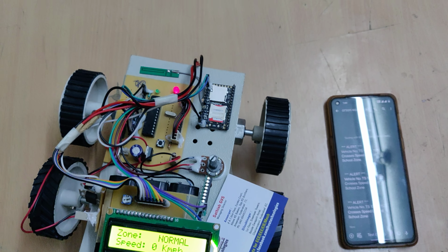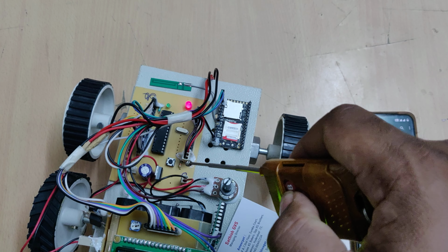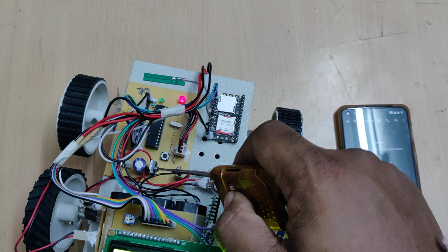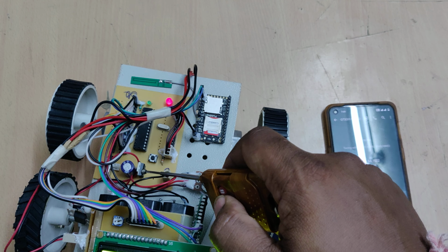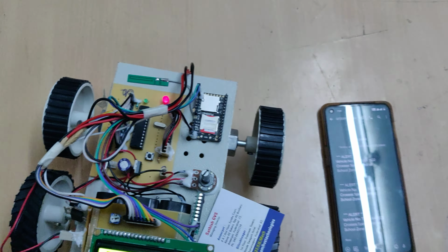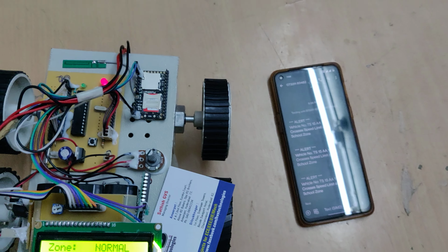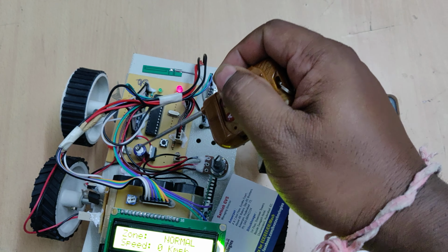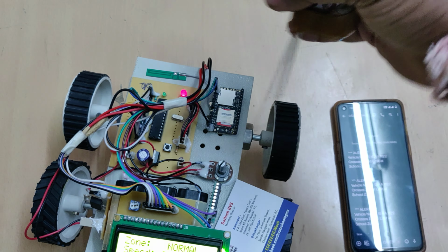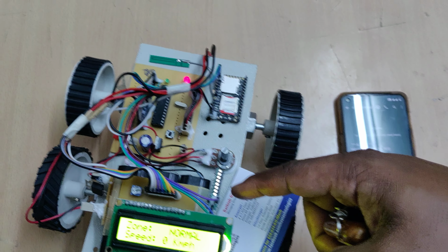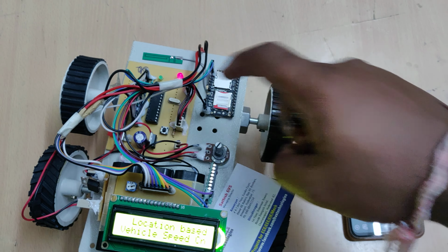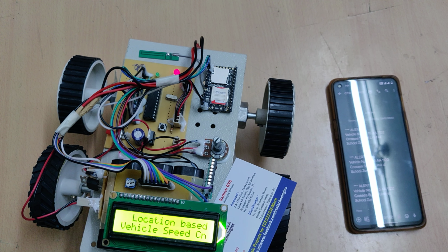Right, so coming to this motherboard, we are providing 12 volts input to this, and after this 7805 regulator we will get a constant 5 volts power supply, which is the main operating voltage of the microcontroller and the input output modules, along with the GSM modem, RF and LCD. Once the power supply is given, the microcontroller starts working by reading input from the RF and controlling the outputs along with the GSM. And this is the reset switch to restart the microcontroller.